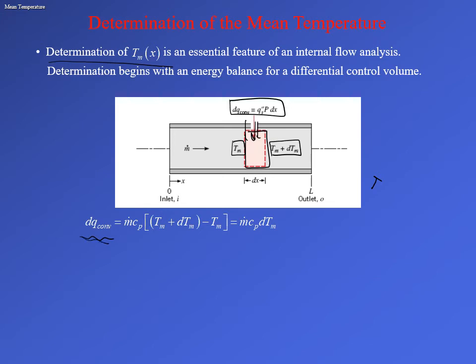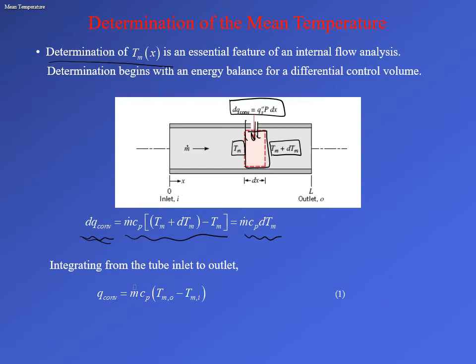is ultimately increasing the temperature of the fluid. So this is in watts. So this is m dot, which is the mass flow rate, times Cp, the specific heat, times the temperature difference it results in. So this energy results in the increase in temperature. So that becomes m dot Cp times dTm. Okay, and this energy, if you want to calculate, you can also write using this relation, which is Qs double prime, the heat flux, times the small area through which it is convected in, and that area is the perimeter of the pipe, times dx.